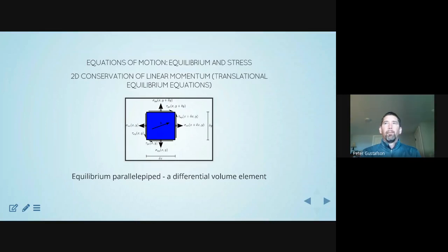So let me say it this way. If you were given that problem on an exam and you had repeated roots, and then you defined for those repeated roots unique principal stress directions, you would be wrong. And so I would mark you down for that, because they're not unique. They're arbitrary. They could be any set in that plane. So it wouldn't be that your set was totally incorrect, but it's not the complete and correct answer. You're never going to have more than 3, if that was the other part of the question.